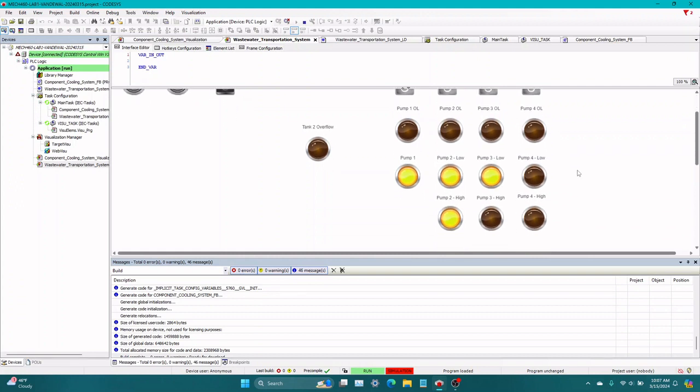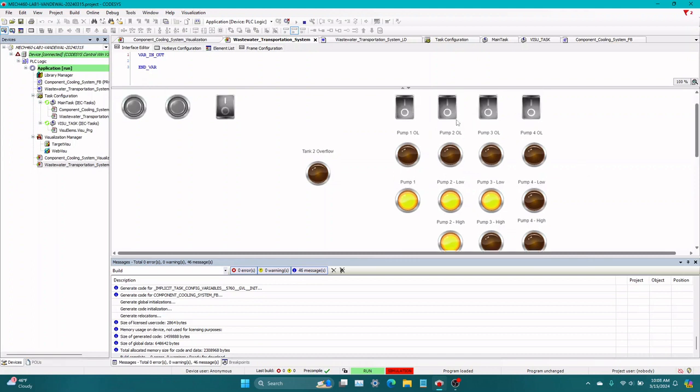This is because in a real world environment, if only pump 2 is supposed to run but the overload is on, you still need a pump to run. So it would just switch it over to the next pump until the one with the overload on is fixed.